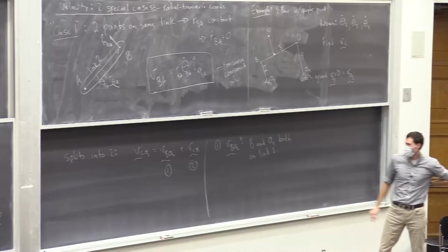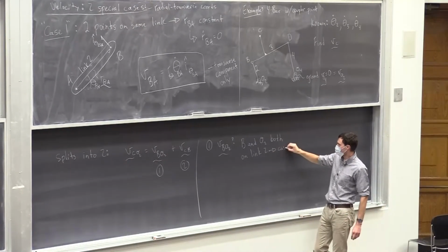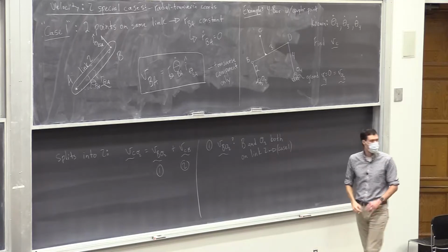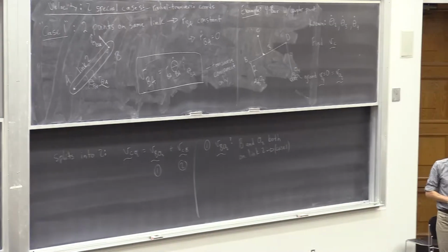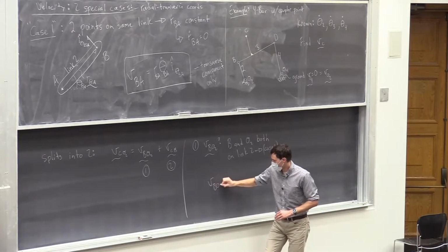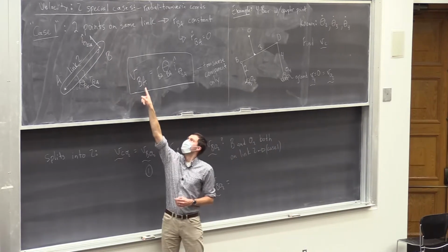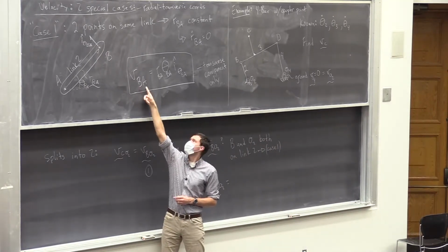Okay, so as soon as you identify that, which you'll get really good at identifying, you can say this is a case 1. A case 1 scenario: 2 points that are on the same link. That's going to allow me to write my velocity of B relative to O2 really fast and easy. It's this one here. So we're going to sub in B, and instead of A, we're going to have O2.